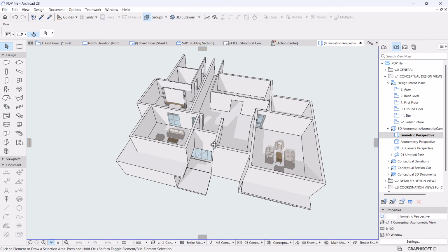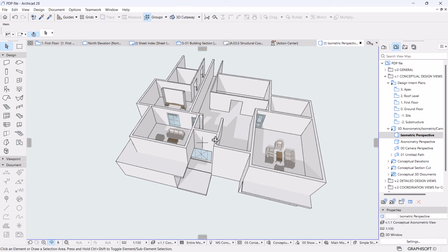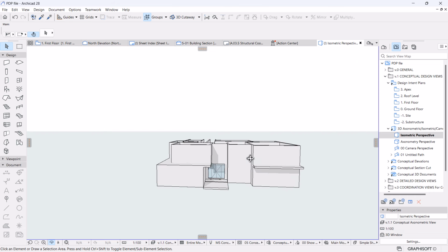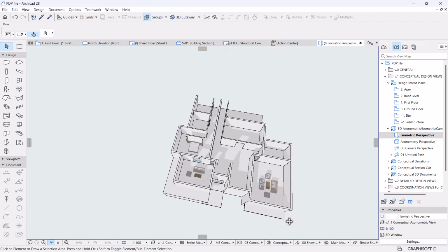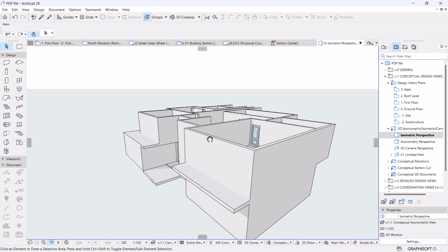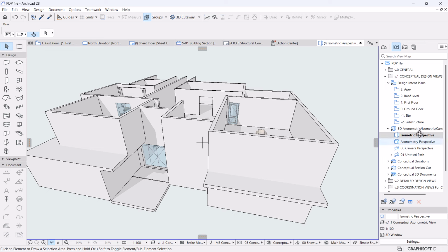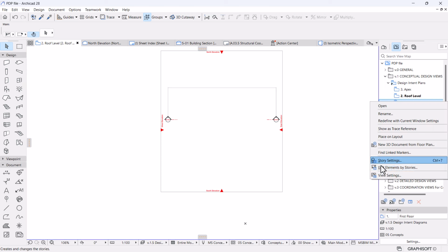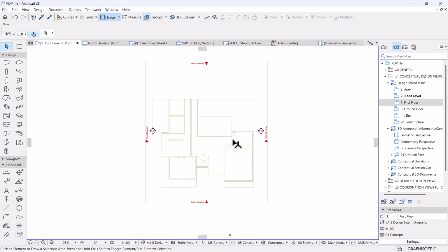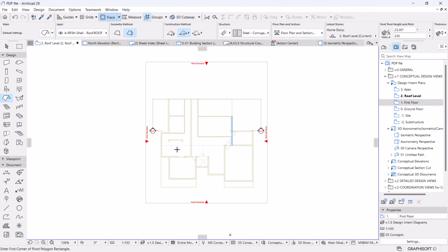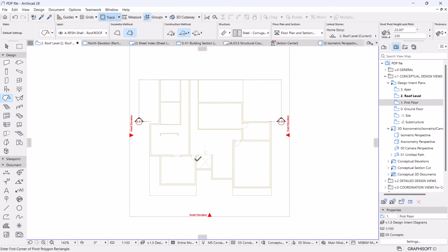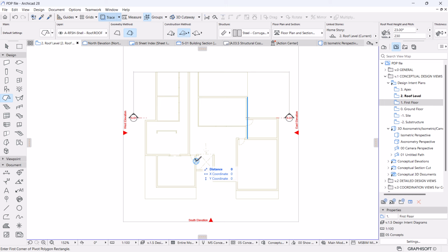Great. So let's quickly now plan around the roof geometry, because it's very important. It will give us a direction on what kind of elements to add, before we add elements that are not really addressing the needs of the roof. So I'm going to go to the roof level and right click on the first floor to show as a reference. What I need to do is to activate the roof, but before I place, I need to decide which areas. It's always ideal to do your roof in portions instead of holistically. Okay, but that's clearly the approach on this one.